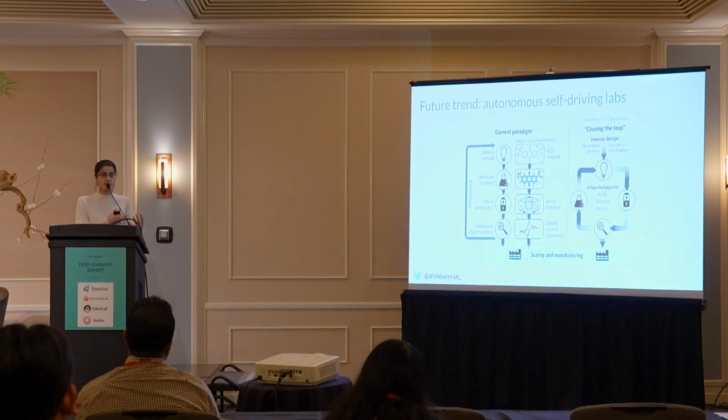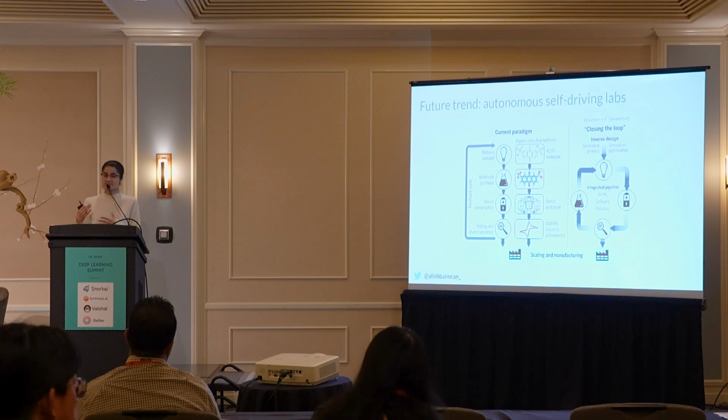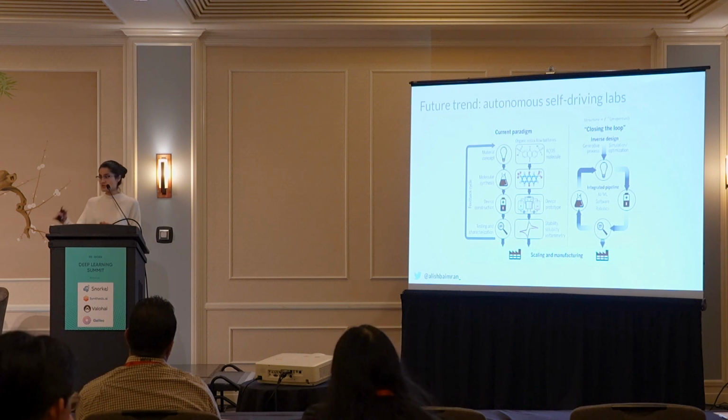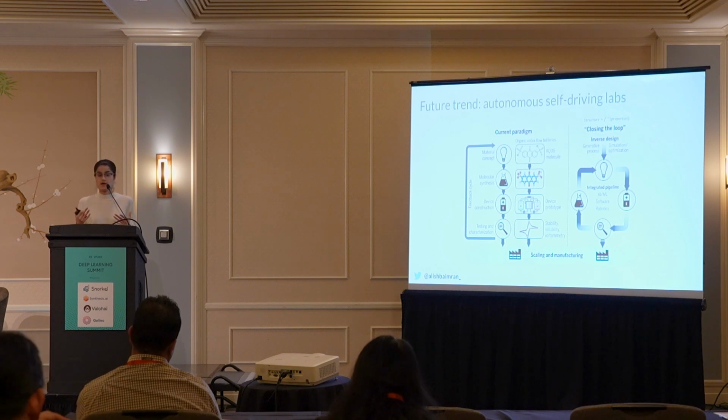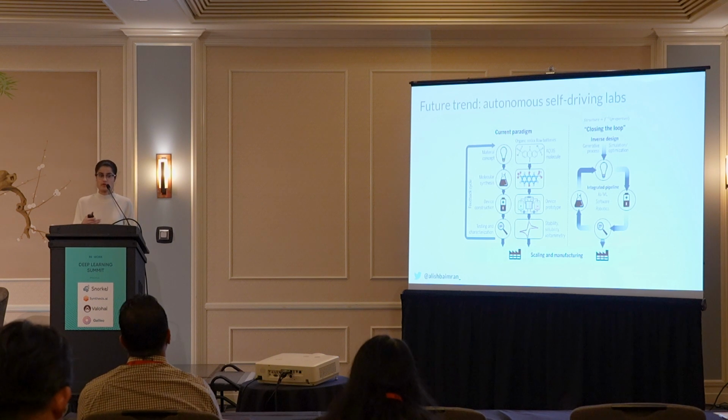But you can imagine it's a very, very manual process where you have technicians standing in a lab just charging and discharging their cells and then measuring the degradation patterns over time to be able to say, this is the capacity and the decrease in resistance in our battery cell over time. And so that process, like I said, takes months, even years. And so there's a lot of work being done to speed that process up, because that's where a lot of the closed loop happens, when you're able to test your device and use that data to then iterate on your concept and your materials design.